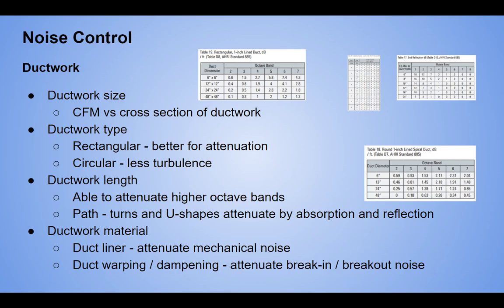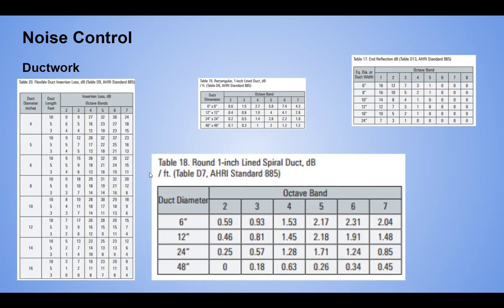And so if a noise jumps into a duct from another space, so what do I mean by that? If you have a duct running across a scene shop and somebody's working in that scene shop and that goes into the auditorium and somebody's running a table saw and you don't have proper wrapping or dampening, or you haven't taken the precautions to build around and isolate that duct, that noise is going to jump into that duct and then it's going to come out on the other end at the diffuser. So we want to avoid that.